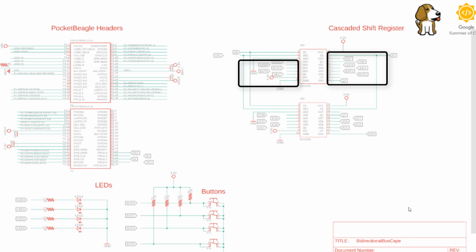We can take input from these IOs, can shift them inside the PRU, or can connect some LEDs or some other peripherals and control them and give them output. So with just 4 pins, we can have a lot many IOs, which otherwise we can't have.